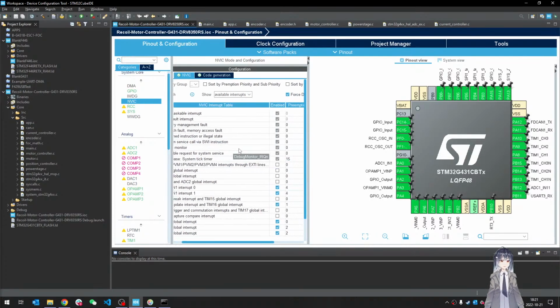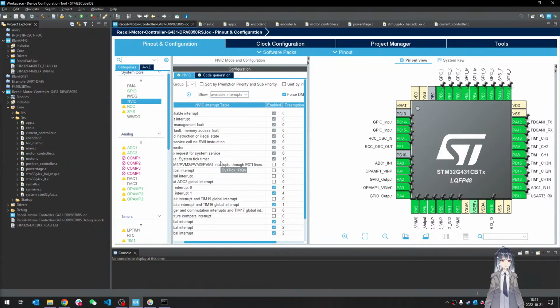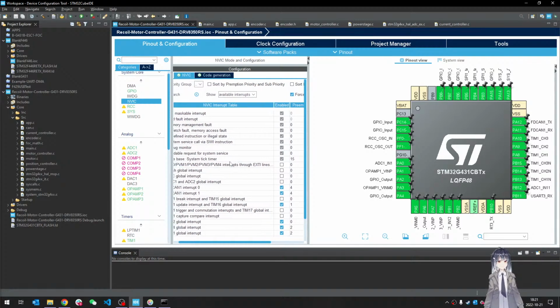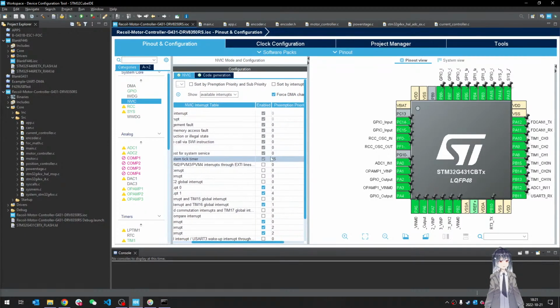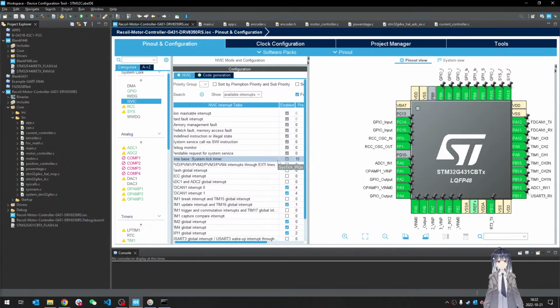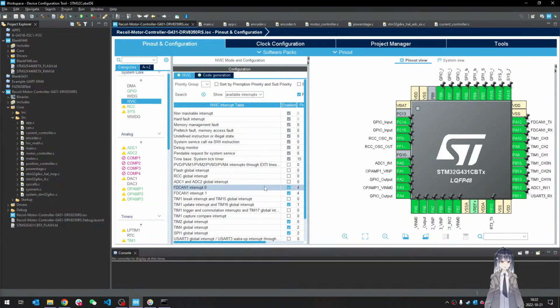Basically it watches the system tick, and if the tick increases to some threshold, it determines that it has timed out and exits with the error state. But that system tick is incremented by an interrupt handler which is at the lowest priority. So inside any ISR routine, the system tick will not be incremented because you are in a higher-priority ISR than the system tick ISR. So you cannot use any polling functions inside the ISR routine.